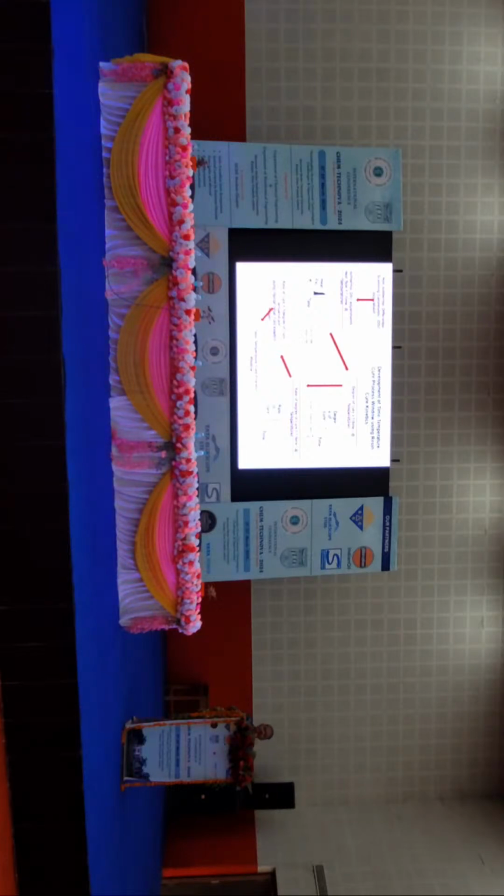So from this heat flow plot, you know that it is heat flow versus time. You have the area under the peak, right? Total area is called the total heat of reaction. At any instant of time, if I take the partial area divided by the total area, you will get the cure conversion alpha at the specific time. Next slide, please.